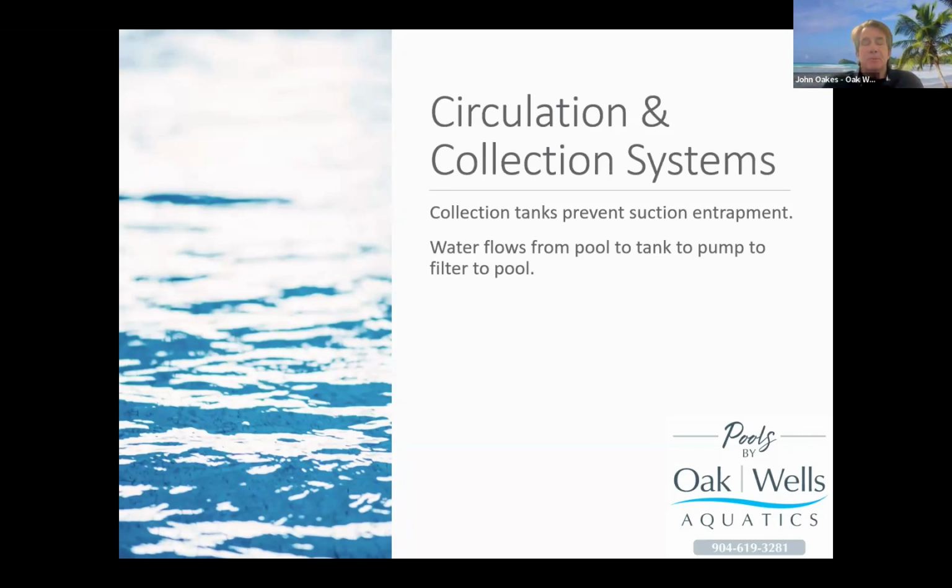Typically, I'd say a majority of the commercial pools that we deal with, there'll be an equipment pack system, which you may be familiar with the term vac pack. That's a brand name. There's another company called AquaWorks that also makes packs, and a company here in Jacksonville called Compact makes equipment packs. And this is a fiberglass coffin type box that typically contains the pumps, in some cases, the filters, the collection tank, and all the other equipment that it takes to run the pool. Next slide, please.